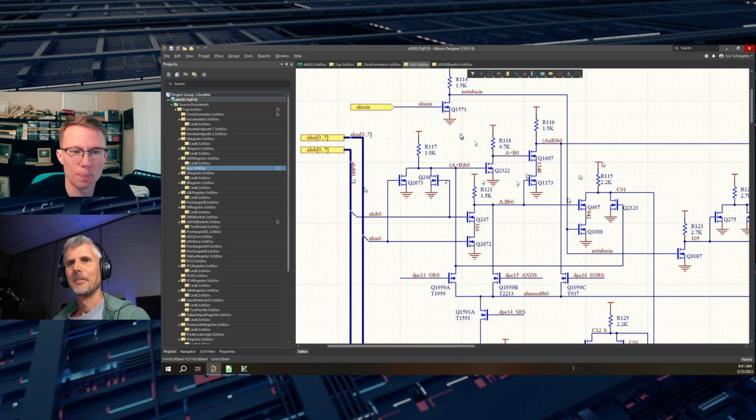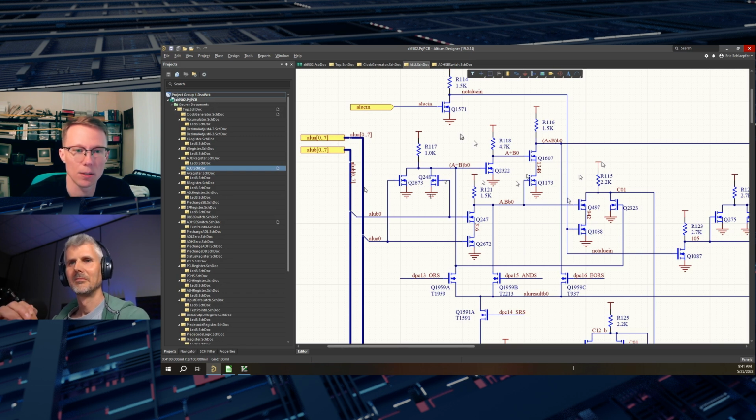Because everything is effectively open drain, at least in the 6502, they need bus pull-ups. And in order to save power, among other reasons, those pull-ups are not always turned on. So they have a two-phase clock, and on one clock phase, they pre-charge the bus. They take all of the bus lines on all of the buses and charge them all the way up. They're not quite 5 volts because, again, all we have are these depletion mode MOSFETs. So because of threshold concerns, you only get up to a certain maximum. I think it's maybe 4 volts. It's probably less here in the MOnSter 6502 because the transistors are different.